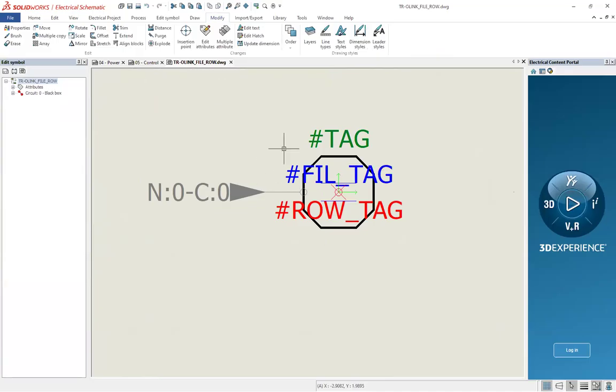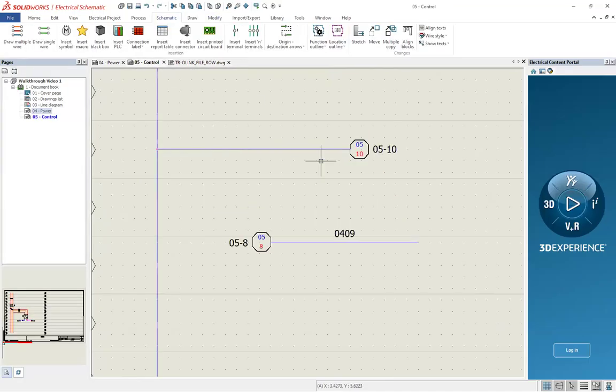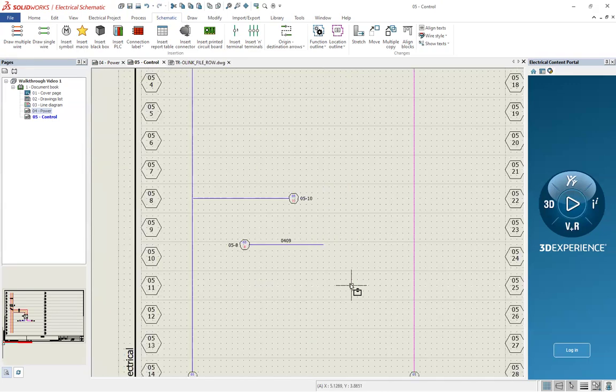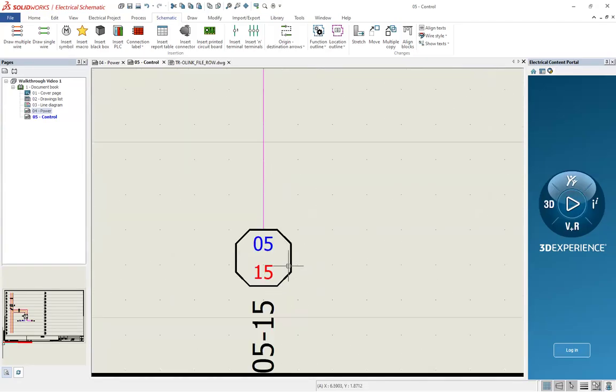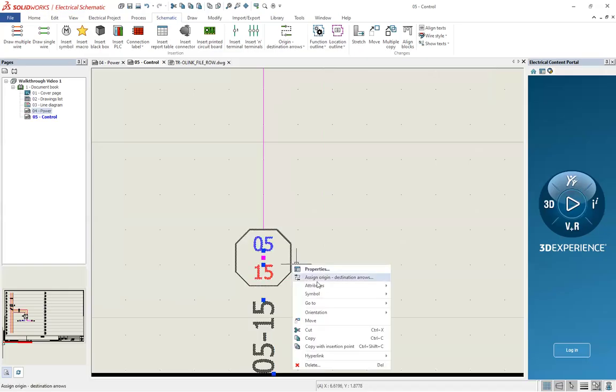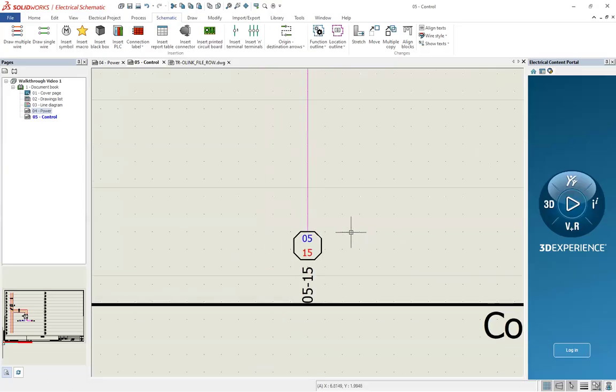Like this is the way, right? This is which one? This is origin. So this one's correct. This one's technically backwards. So what might happen is you might insert it, even though we fixed it, and your numbers might still be upside down. All that takes to fix, should it happen, once you have corrected it the way I just did, is a quick symbol update and it'll fix itself.